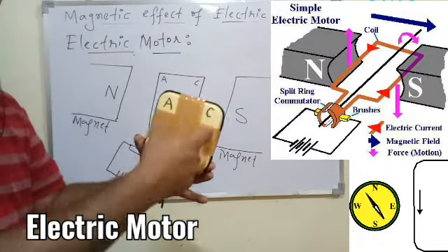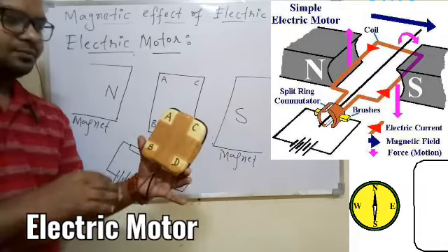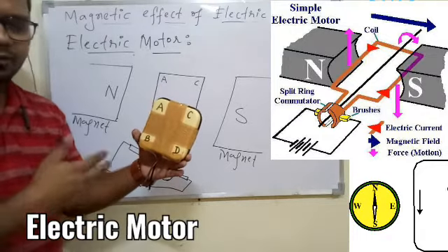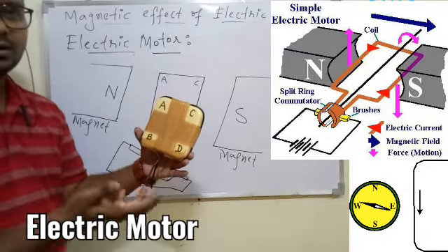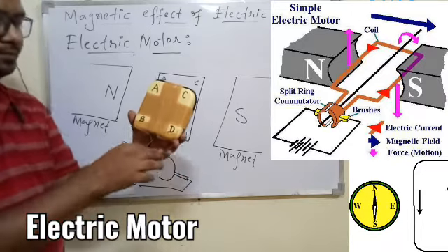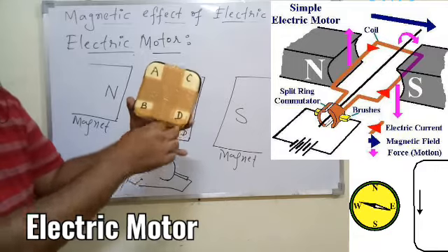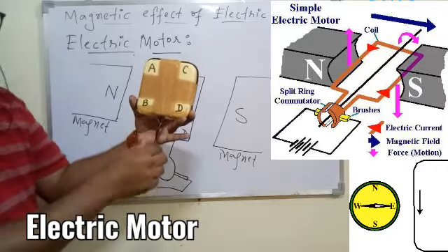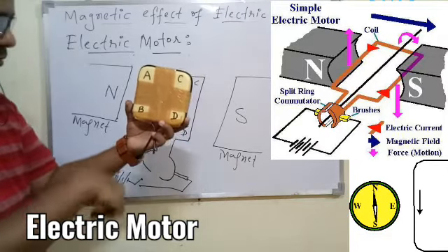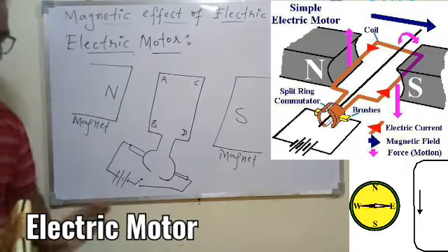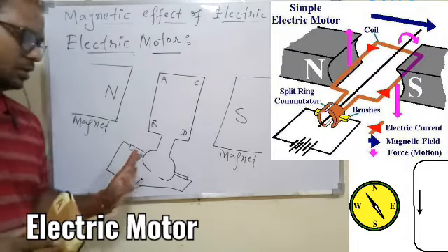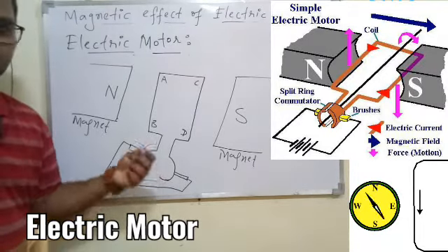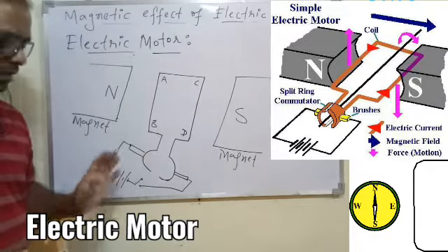So we got a rectangular coil which is nothing but made up of iron, and then over this iron we have different turns of the wire, many turns are given. So overall we are trying to make the coil-like structure a kind of electromagnet, and these two wires which are coming out, the two different terminals of the same wire, will be given the support, and finally this will be connected with the help of two different rings, half ring this side and half ring other side, and this is also called split rings. Why split? Because it is half and half at one side, so we can say one ring has been split into two, so half ring and half ring, it is called a split ring.